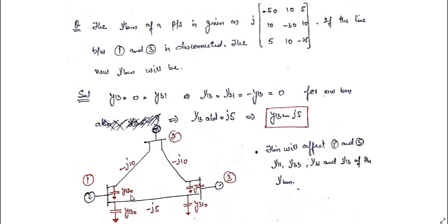Here we haven't calculated the shunt admittance, we just know the shunt admittances are there. This is bus 1, there are shunt elements. Bus 2 also has some shunt element because this sum is also not equal to 0. All have shunt elements. I have not shown it over here, but from this you can calculate it. There are shunt elements present over here also.